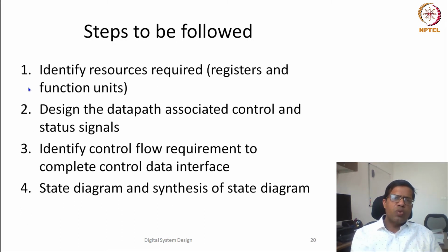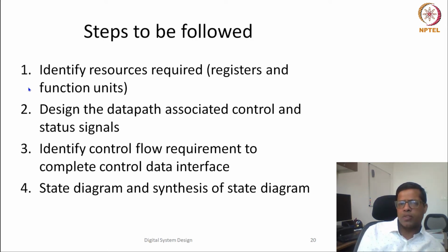So there are 4 steps which we can follow. The first step is that we will identify what all resources are required. Resources means hardware here, and it essentially means what all registers are required, what all memory units are required, or what all function units are required. And in those function units, whether this is addition, multiplication, subtraction, or shift operations, or decoders, multiplexers, all those resources we will try to identify.